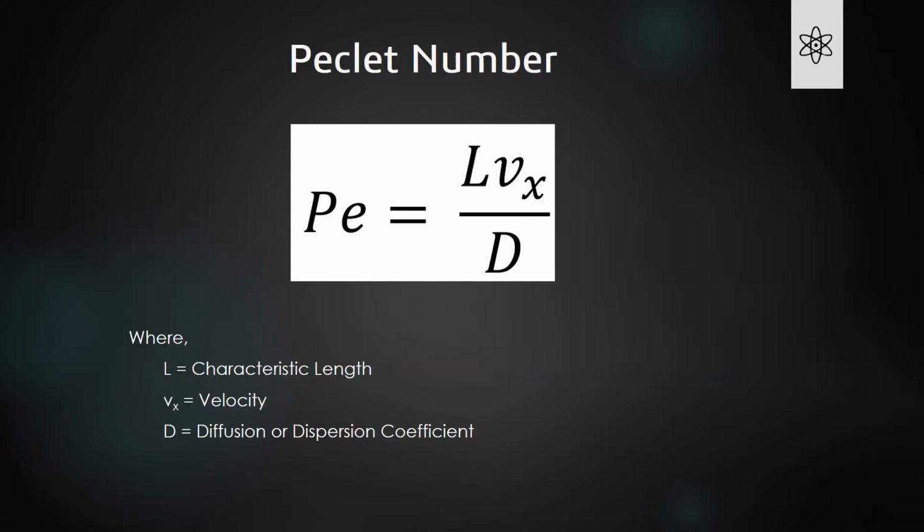Another relevant value used for this experiment was the Peclet number, which is calculated by the displayed equation, where L is a characteristic length of the reactor, V is the velocity of the flow, which is calculated by dividing the surface area by the fluid flow rate, and D is the diffusion coefficient, which is constant for all the trials. The lower the Peclet number, the higher the mass diffusion. To achieve higher mass diffusion, the experiment should be run with a low flow rate.